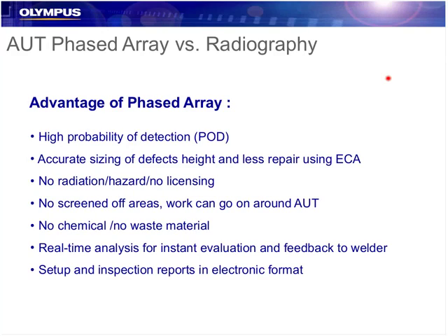And one of the huge benefits is real-time analysis. We saw the strip chart recording. We'll see that a little further in the slides and maybe actually in the program itself. Based on the strip chart recording, we're able to quickly see if the weld is good. This is really critical especially offshore, because often as soon as the pipe is inspected, they want to be able to take the pipe and install it underwater. And even onshore, we want to keep up with the welding process. We don't want to be too many welds behind. So the strip chart type recording really allows real-time analysis.